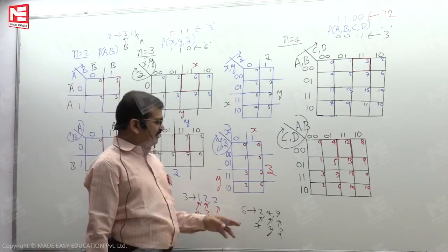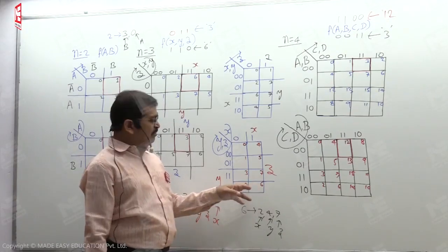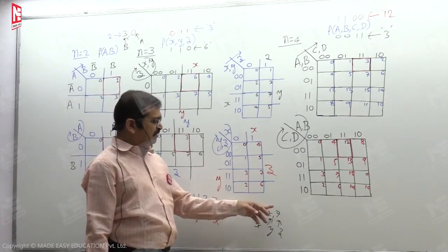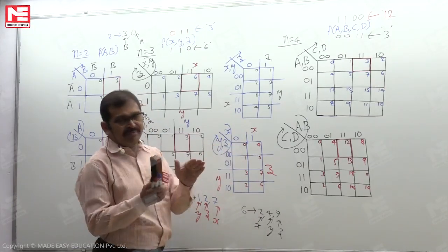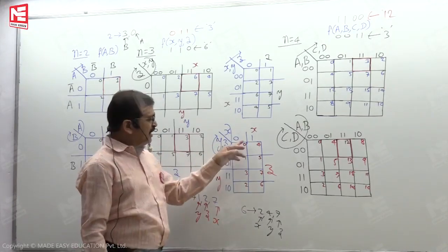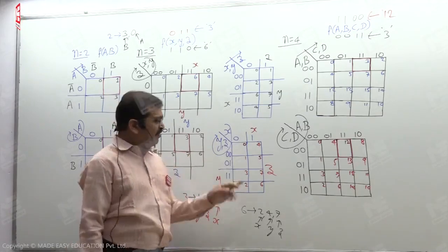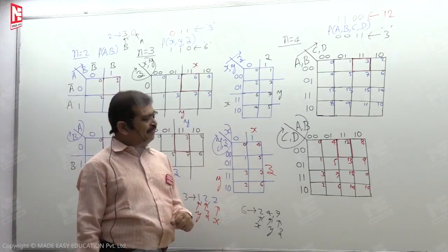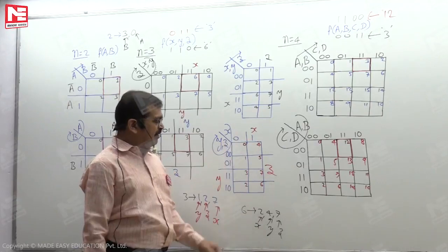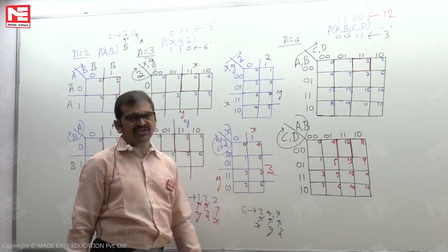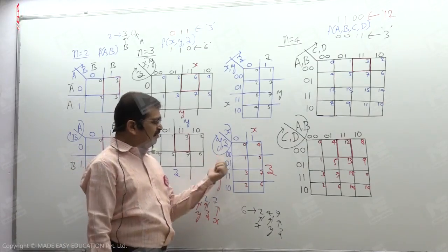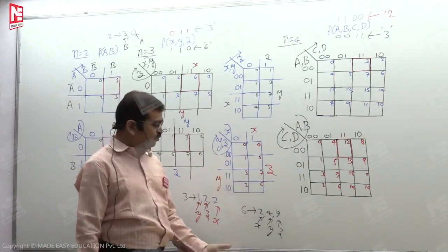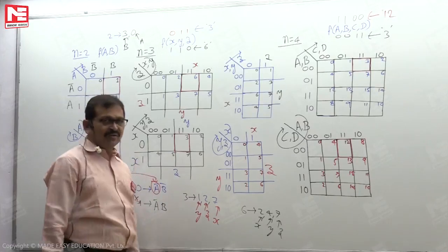Even if you look here, the reference cell is 6. The common line directly we see is with 2 and 7. And if you fold this K-map vertically, this line will overlap. Whenever these 2 lines overlap, between cell 6 and 4 there is a common line, so cell 4 comes to be an adjacent cell. And also you can see they differ in variable y, and of course in other 2 variables so and so.